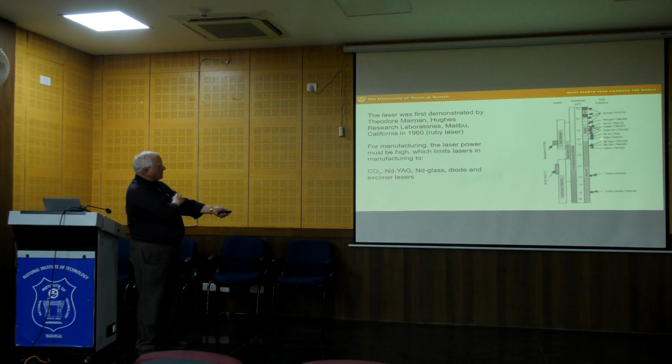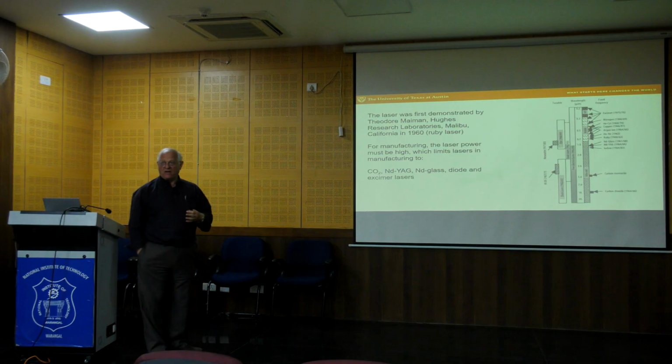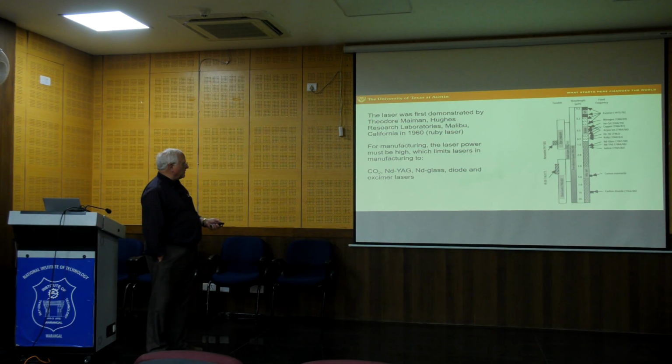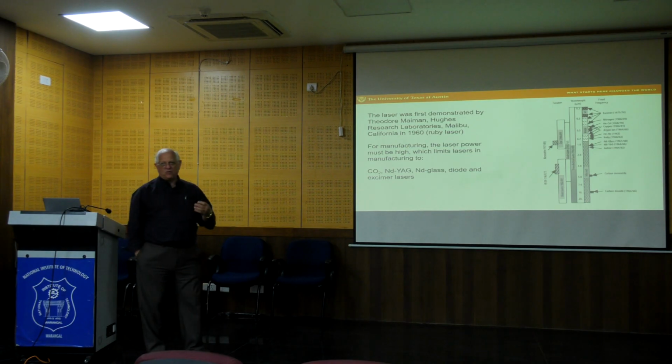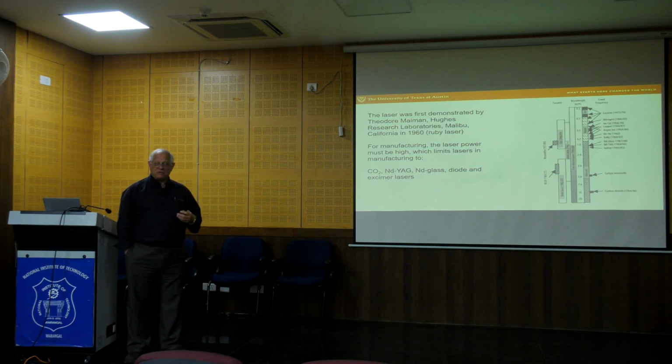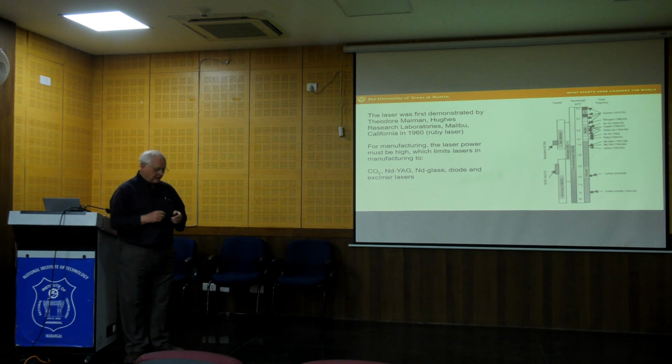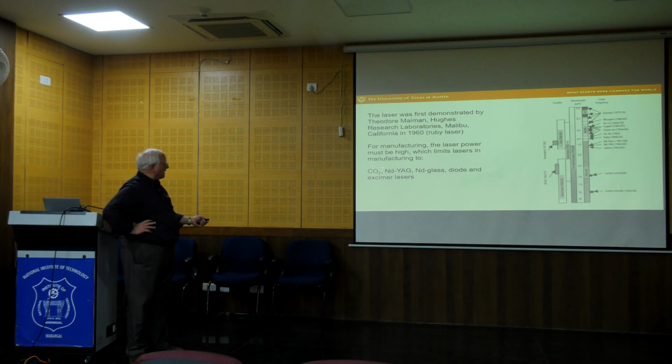Then we see over here the material used in the laser and the year of development of that. And so if we come down here to the sort of the UV world, we see the CO2 lasers down here. And again, for manufacturing, we have to have power. It's the energy deposition rate that must be high to use lasers in manufacturing, whether it's for additive or something else like cutting or welding with lasers. And so that kind of limits the lasers to this group.